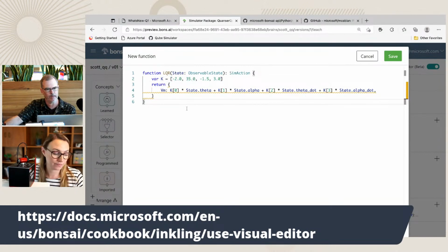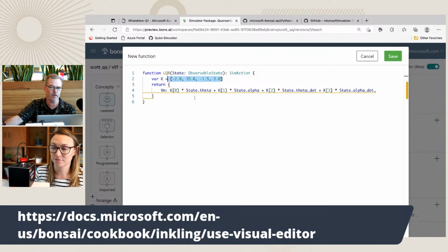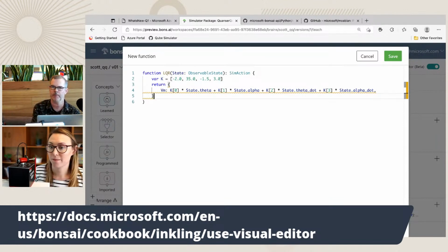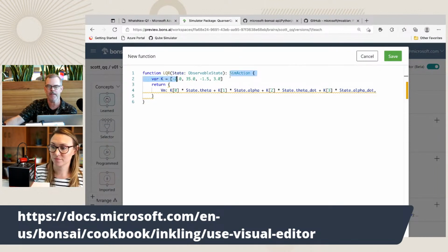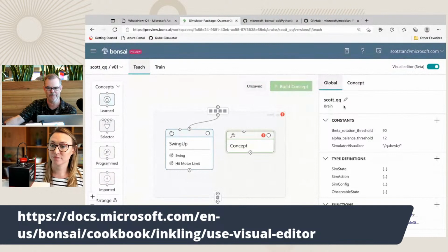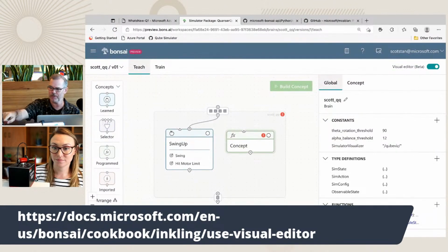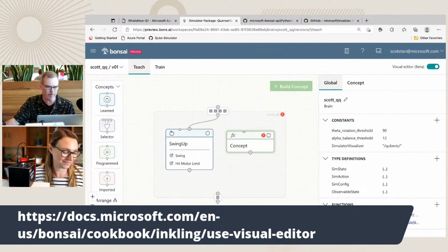Yeah, and these results were achieved empirically. From the simulator, we solved it near this space, and that's how we were able to come up with this vector of 4 numbers. You could also pull these out of your simulator in Simulink. So we're able to solve this piece. But it's funny, we'll see that these values were derived from a different sensor, a rotational sensor that had very little friction. This one adds a bit of friction, so we have an interesting bit of behavior that we hadn't seen before, but it's kind of fun.